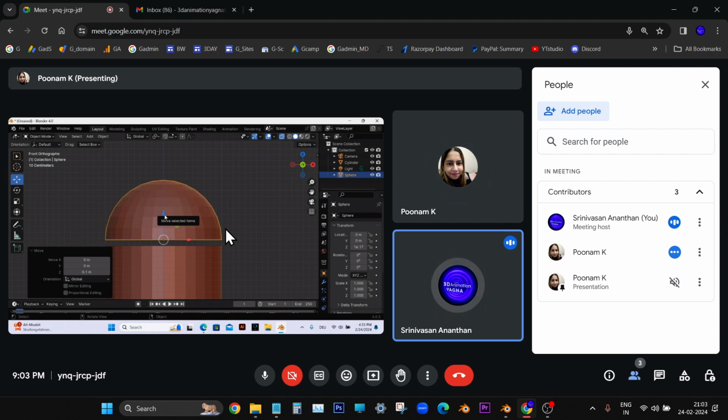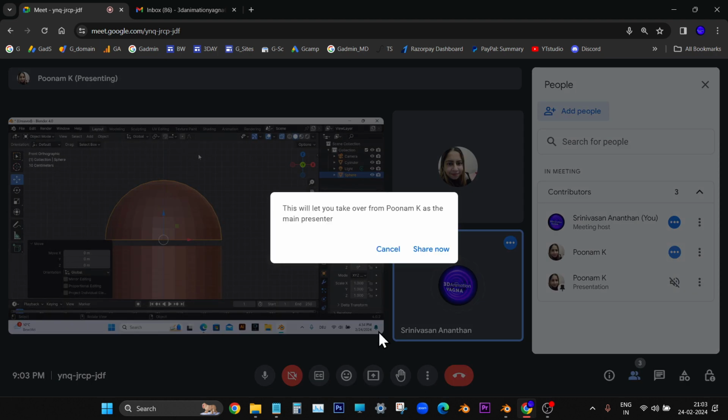So we can hold Control, or on the top you are seeing the horseshoe magnet icon. Yeah, that one. If you switch it on, you don't have to press Control. It will happen without pressing Control. So the shortcut for that horseshoe magnet is Control. Press Control and move it. Now this gap we need, actually. I will tell you how to fill that. So I'll share my screen.